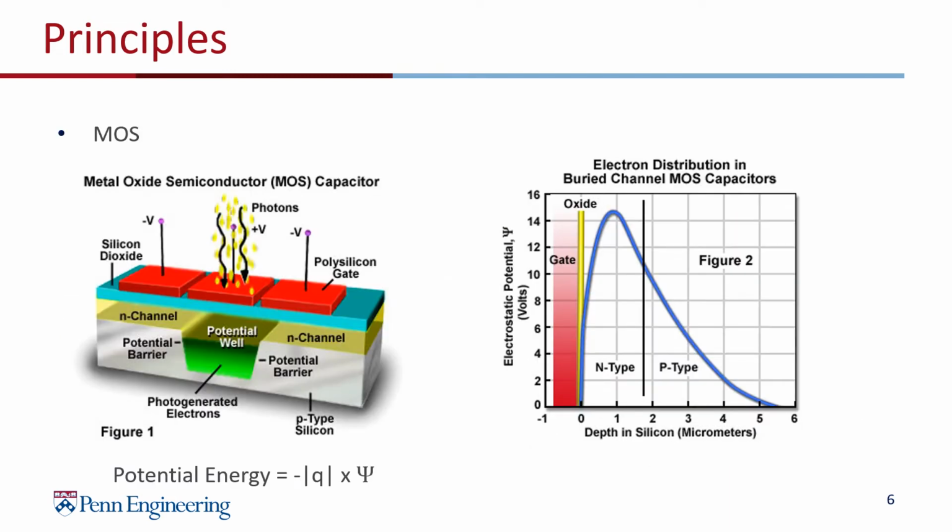The most important part is the MOS capacitor. In general, there are two types, one having a surface channel structure, while the other has a buried channel design. In CCD, we use the second one. The MOS capacitor array is fabricated on p-type silicon, in which the main charge carriers are positively charged particles called holes.